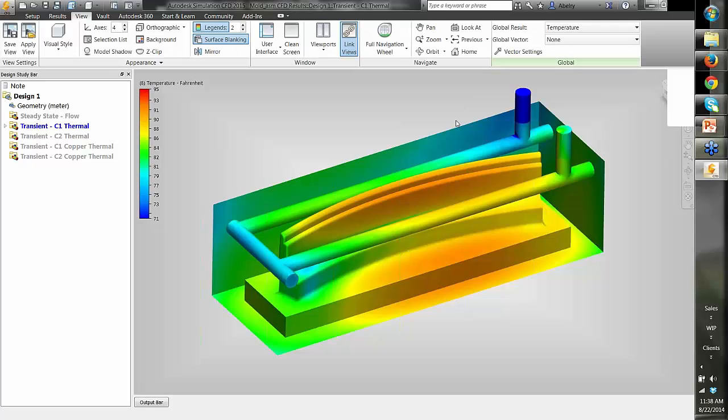Very good. So what I want to do is show you the same model, the exact same model, run the exact same way, but really just introducing the CFD interface and the CFD workflow. And you might be asking yourself why. What Brian just went over is really leveraging some of the CFD technology to give you the best of both worlds in Moldflow. So you're running the cooling flow channel with the CFD solver, and then you're doing everything else with the Moldflow technology.